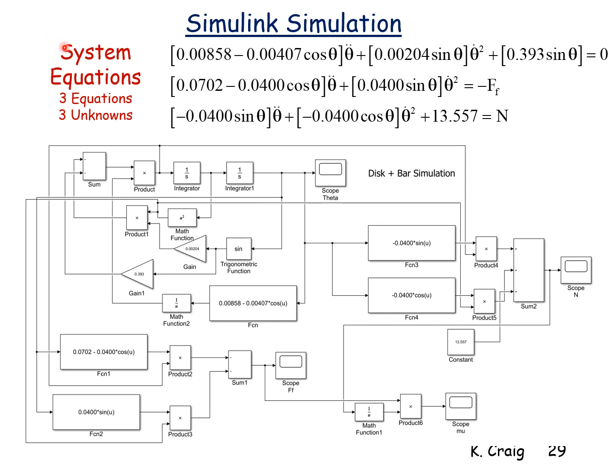Here I've summarized my system equations. The first equation is the equation of motion. It only contains theta double dot, the angular acceleration, and no unknown forces or torques. This will describe the motion of the system. Then I have an equation for the friction force and an equation for the normal force. I've left the equations substituting values for the parameters. It's not something that I recommend you do.